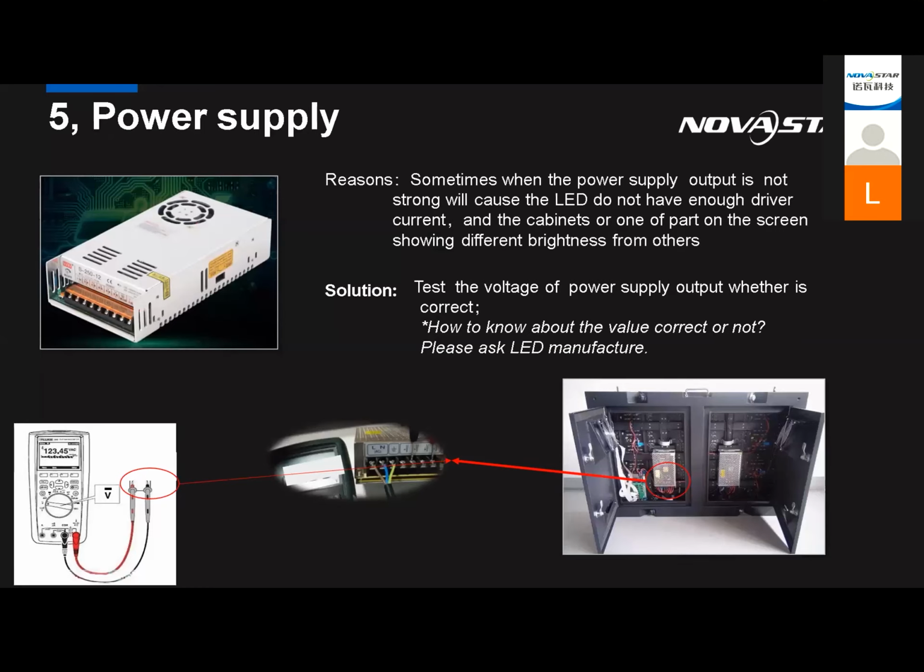The fifth reason, power supply. So I know some cabinets, they use one power supply for LED panel and the receiving card at the same time. But sometimes the power supply between each panel are different. So this would be a reason.